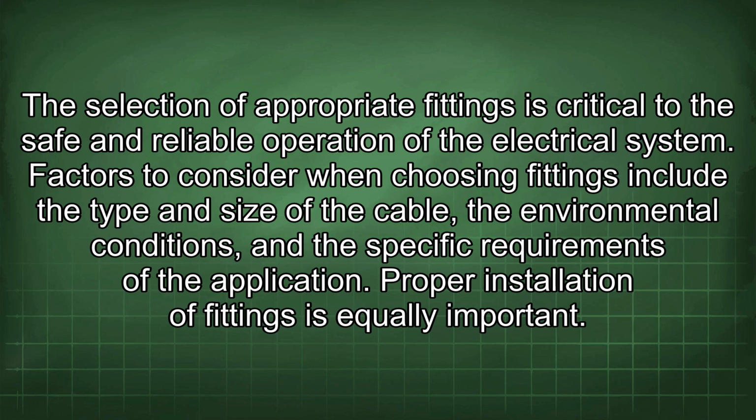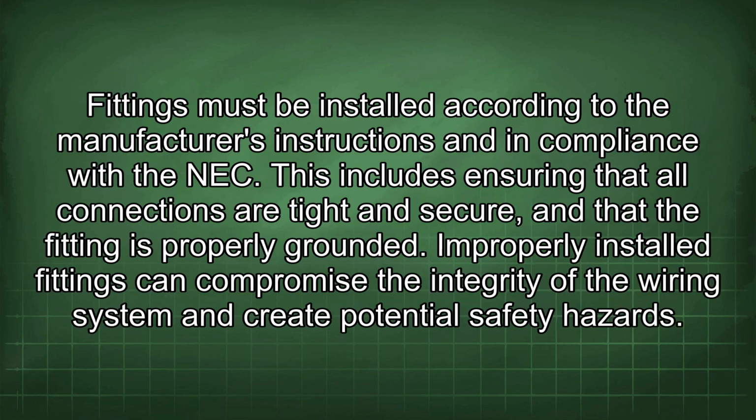Factors to consider when choosing fittings include the type and size of the cable, the environmental conditions, and the specific requirements of the application. Proper installation of fittings is equally important. Fittings must be installed according to the manufacturer's instructions and in compliance with the NEC. This includes ensuring that all connections are tight and secure, and that the fitting is properly grounded. Improperly installed fittings can compromise the integrity of the wiring system and create potential safety hazards.